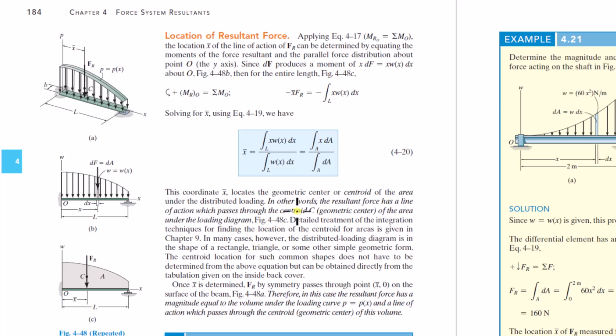That's what they're trying to illustrate. They want to make sure that you understand that you're finding the centroid of an area. So you could go find tabulated results for centroids and use that to get the location of the resultant force, as opposed to having to integrate every time. Okay, so now let's work some problems.